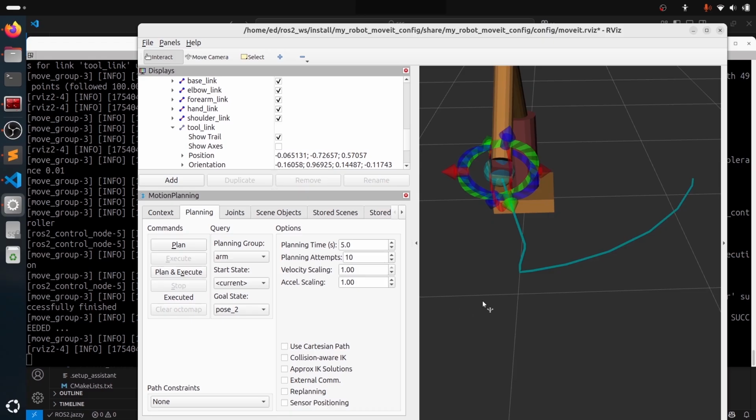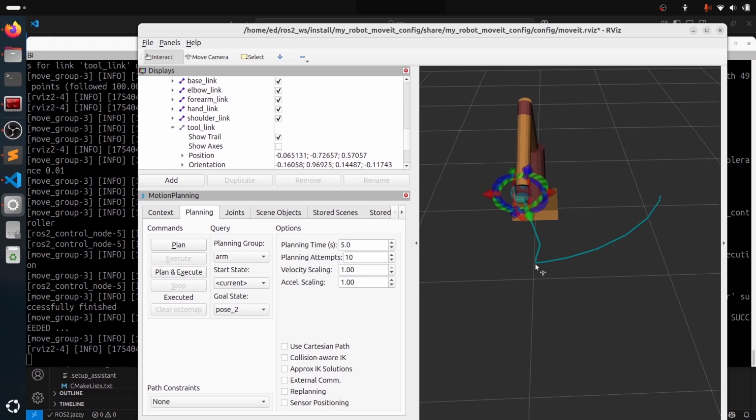It's quite useful. And one thing to note is that with a 6-axis robotic arm, you can do Cartesian path for small distances. But if you want to do bigger ones, and if you want to do soldering, for example, then you might need a 7-axis robotic arm. So you're going to add one extra axis, one extra joint. That's going to create some redundancy. But thanks to this redundancy, it's going to improve the chances of success for the planning of the Cartesian path.